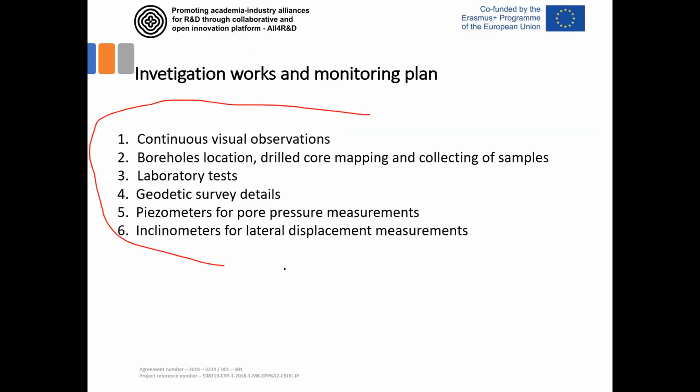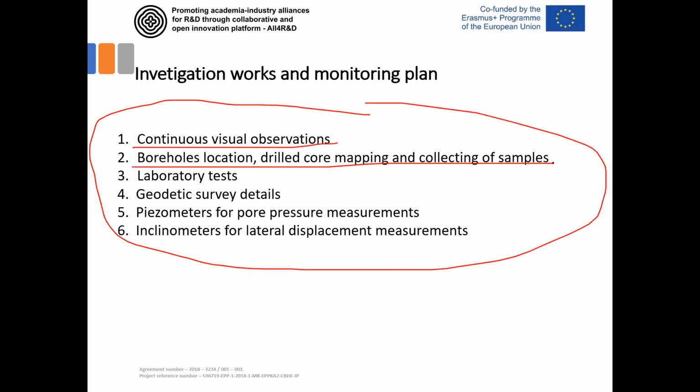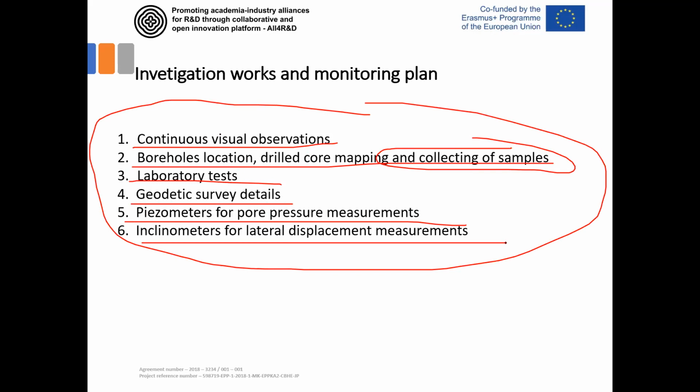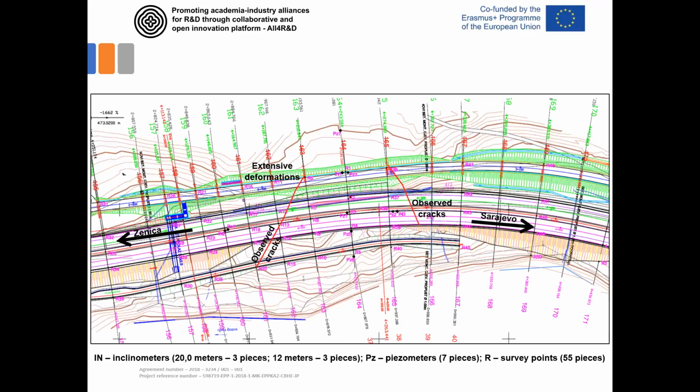Well, plenty of works were performed, including visual observation, borehole drilling and collection of samples for laboratory tests, and a geodetic survey with plenty of fixed points installed to follow its displacement in time. Piezometers were installed to measure pore pressures, and inclinometers were installed to measure lateral displacements along the depth of the potentially unstable area. So here are cracks.